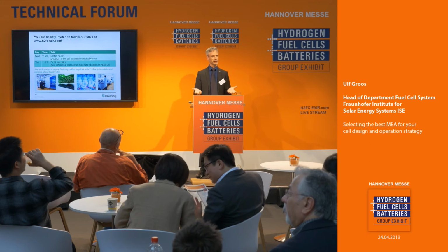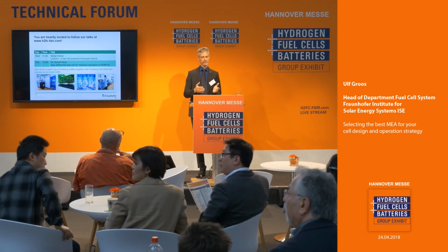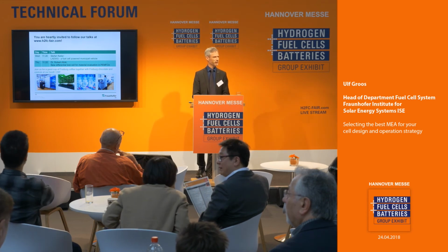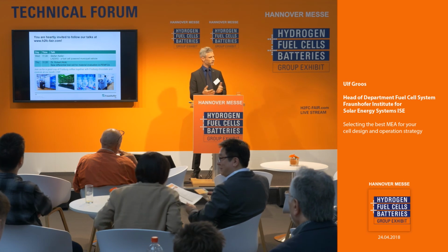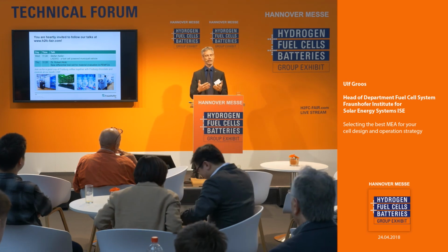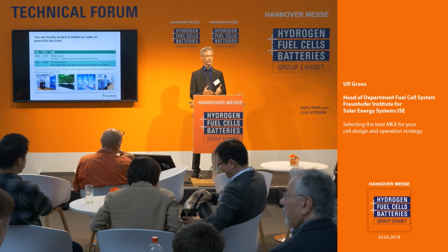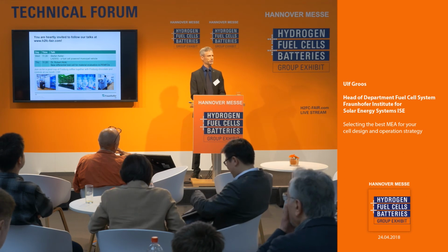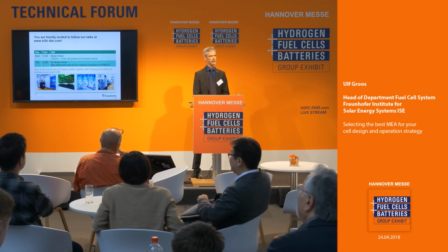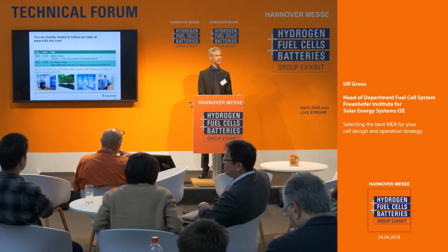So you lose carbon, which we are convinced leads to the pore structure changing. The pores result from the carbon structure that you have as carbon support. If you lose the carbon support, you will change the pore structure. And that's the effect that you can see if you evaluate Knudsen diffusion and molecular diffusion.